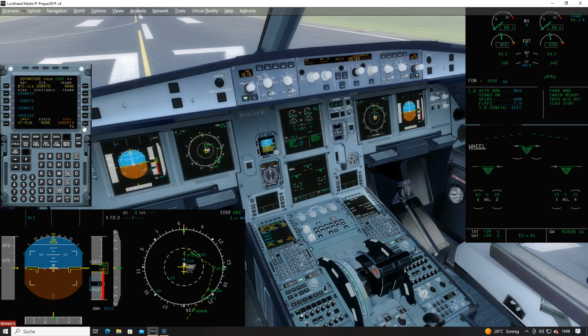We insert the route here. We simply insert. Now we have a departure route, and the destination is the lowest line in this page. We take also the lateral revision page, choose an arrival, and take an arrival to ILS 7 center, the Zulu ILS, and now it's offering arrival routes. We skip this step, we just enter the ILS only, and that's about it.